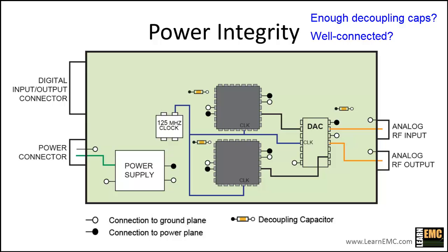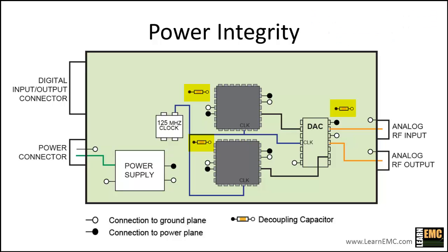We also need to make sure that each of our decoupling capacitors is well connected to the power and ground planes. The 3 decoupling capacitors shown here are connected to the planes through traces. This is never the right way to connect a decoupling capacitor to a board with power and ground planes. For effective decoupling, we need to minimize the current loop area for each capacitor connection. We can do this by eliminating the traces and locating the vias close together. This is the way we're going to connect all of the decoupling capacitors in the new layout.